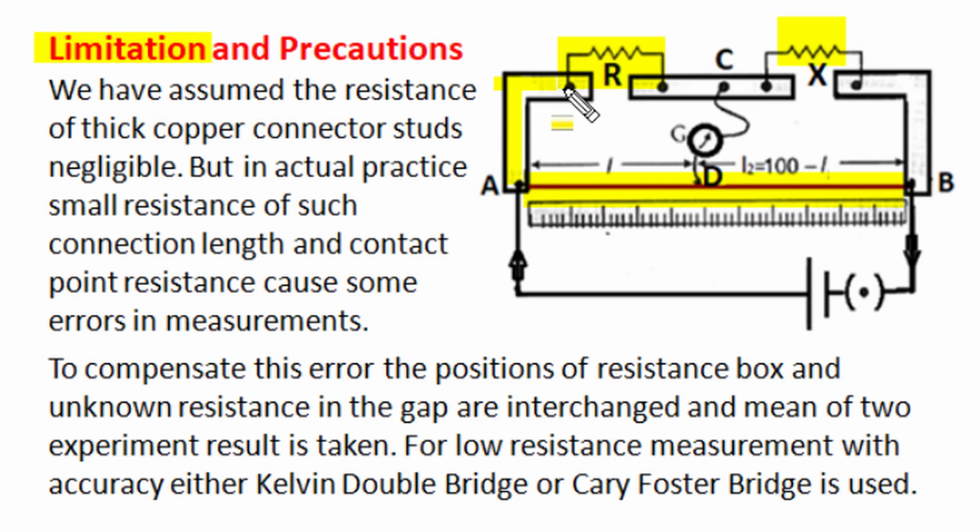For better quality, higher accuracy and more precise measurement, in place of a simple meter bridge we can use either a Carey-Foster bridge or a Kelvin double bridge. Normally for small resistance measurement of magnitude less than 1 ohm we use the Kelvin double bridge.